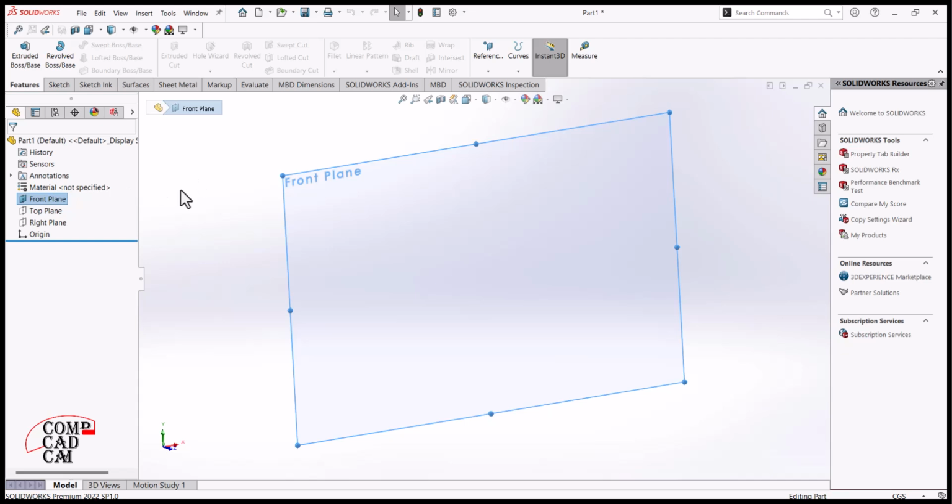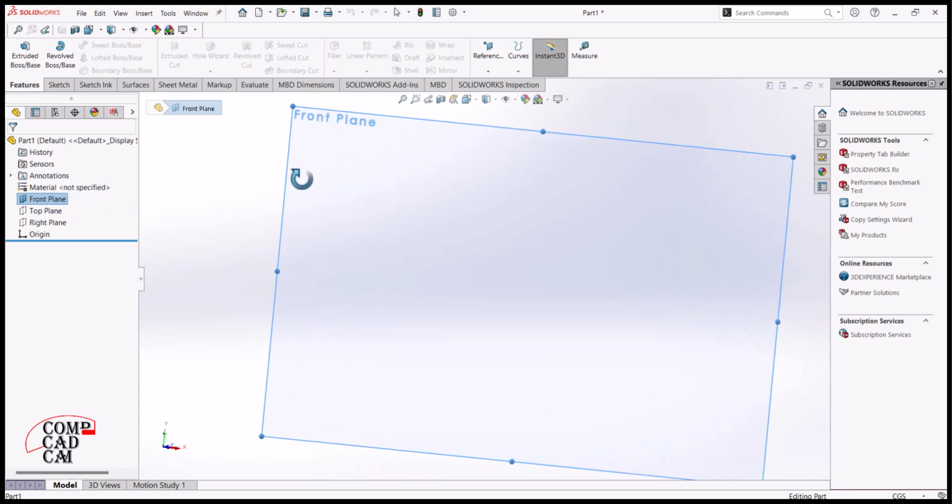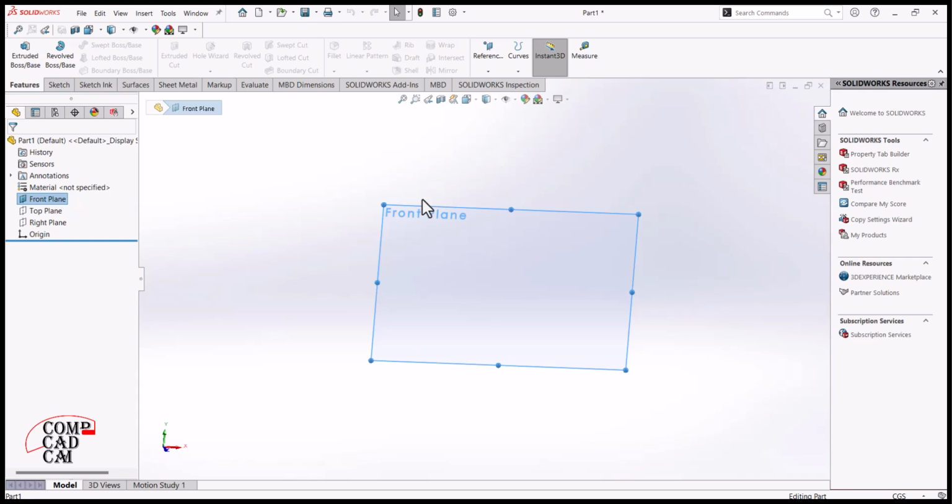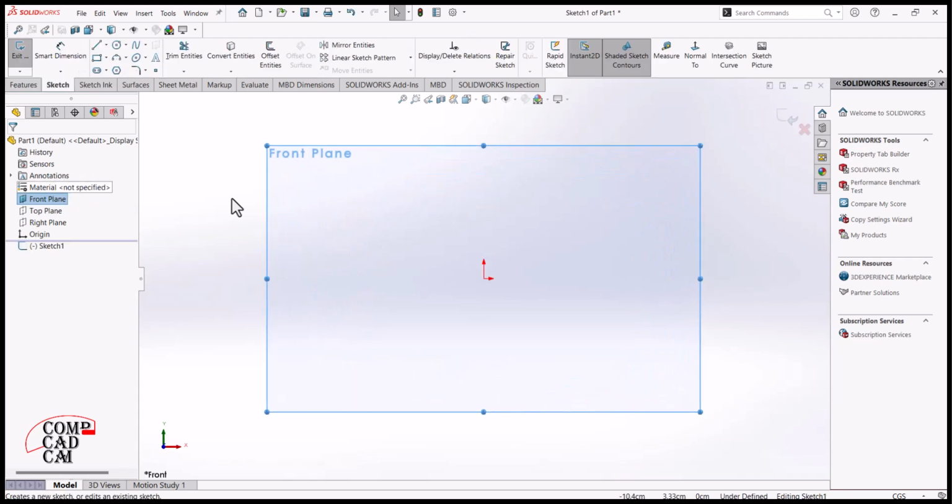And also, once you've selected the plane you want, there is an automation in SOLIDWORKS that makes the plane perpendicular to you or normal to you right from the selection. That is, once you select the plane, then you select sketch, it becomes normal to you, and so from there you start to draw. So this is how the plane selection looks like.